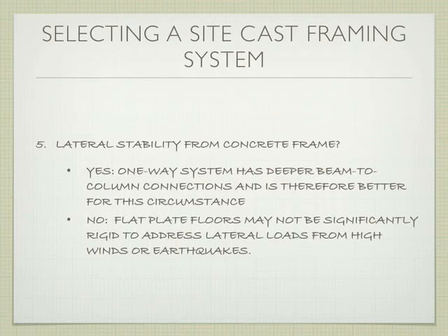So in this particular example, they were going to post-tension this building in Berkeley, and they actually evacuated the neighboring buildings because they were afraid that one of the tendons would break during this process. Once it's in place, and the caps are on and everything else, it works fantastic. But you have to be really careful.